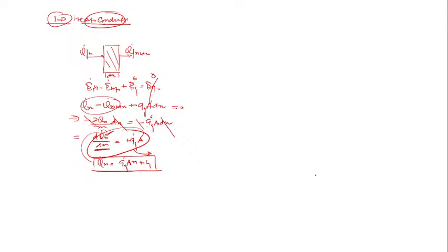But at the same time, if I'm talking about without heat generation, then this term will become 0, and the equation simply becomes dq dot x over dx is equal to 0. So in this case, the rate of heat transfer is not a function of x. Yes or no? But at the same time, flux may be a function of x or not, that depends upon the area.